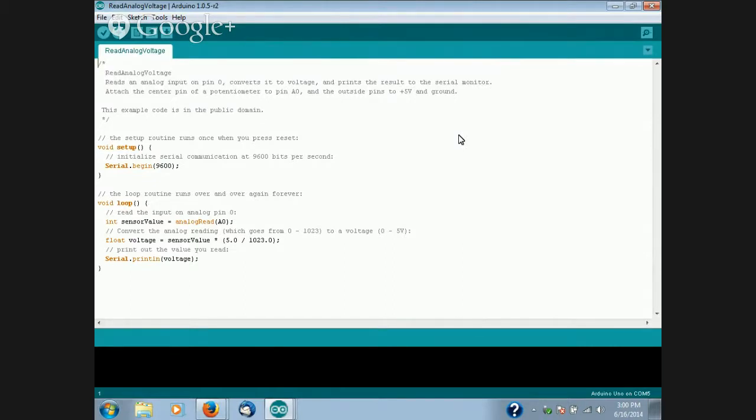Well, they're dividing the millivolts by... No, that's not what they're doing. They're dividing the full scale value by the total number of steps in the digitization. That was what he was telling us earlier, the 5 volts over the 1023. Yes. The fraction.